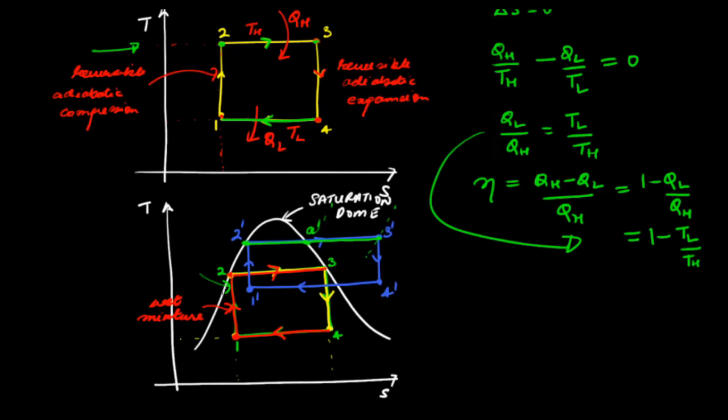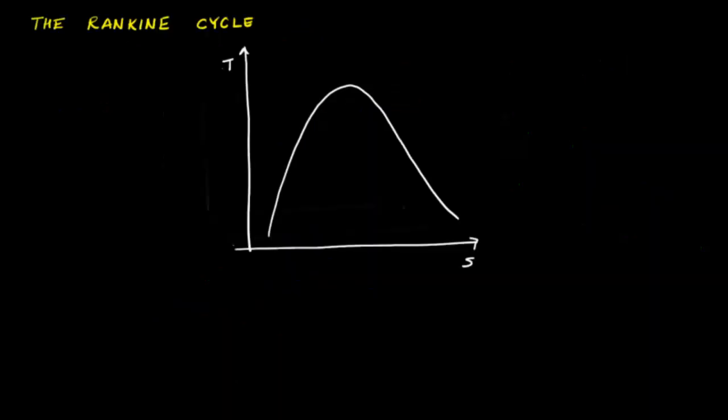So based on this discussion, we conclude that the Carnot cycle is not possible to realize given the various limitations of engineering. Therefore, we need to consider changes to the Carnot cycle to make it realizable. Of course, with the irreversibilities that are associated with real processes.